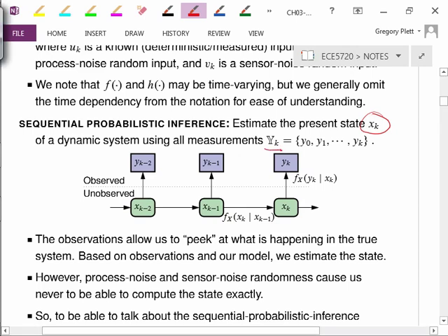First time we've seen this fancy y, but what this means is the fancy y is all measurements at the output of the system from time zero all the way up into right now. So I'm not relying only on the present measurement of voltage right now. I, in fact, am using somehow all of the voltage measurements I've made up until and including time now, and furthermore, well, I don't say it, all of the inputs to the system as well. That's kind of implied. We're also using UK, which is U0 all the way up to little uk. So this is trying to be a fancy U.